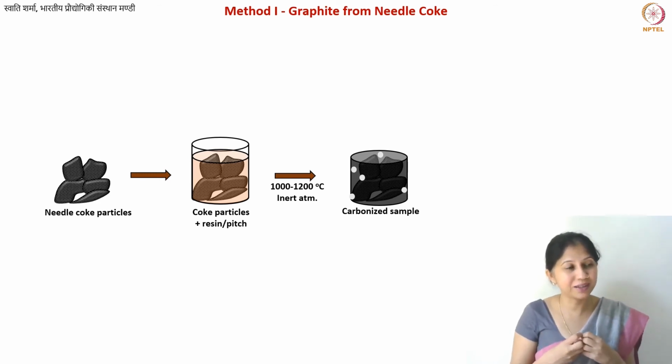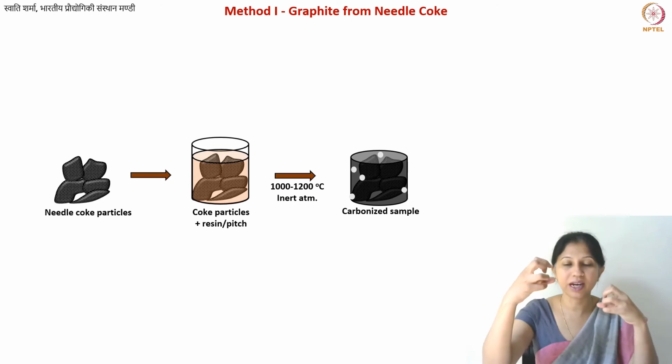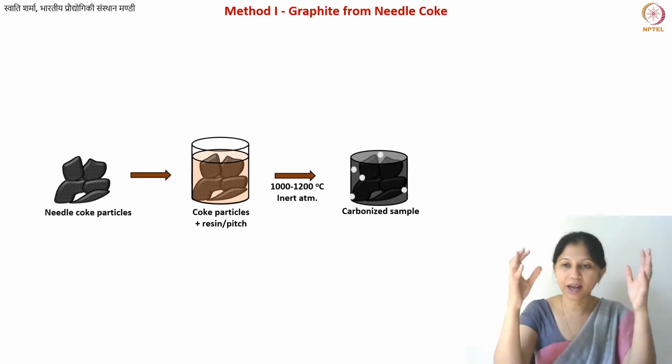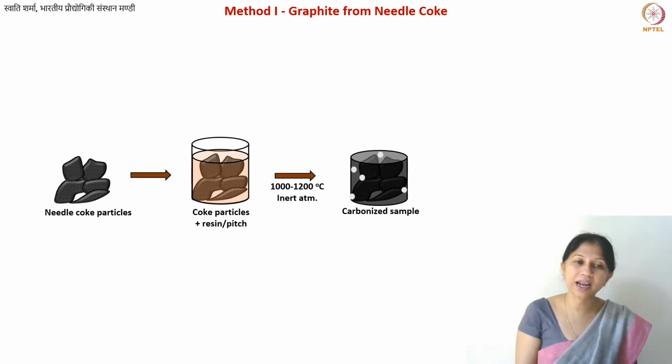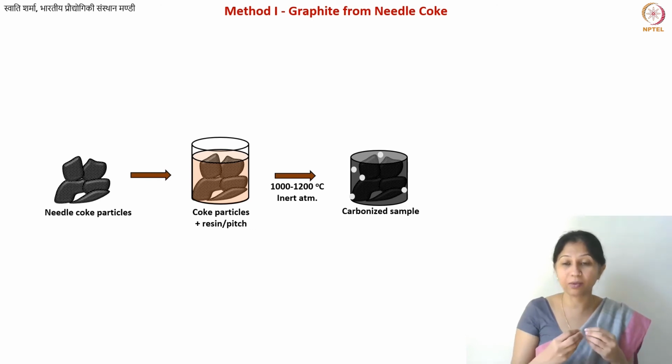Cross-linking basically means that you have different polymer molecules that are attaching to each other, and the overall material becomes hard. That can be done by adding another chemical, which is your cross-linker. It can also be done by just heating. Certain polymers have a chemical property that by heating they will convert into certain radicals, and then they will attach with each other.